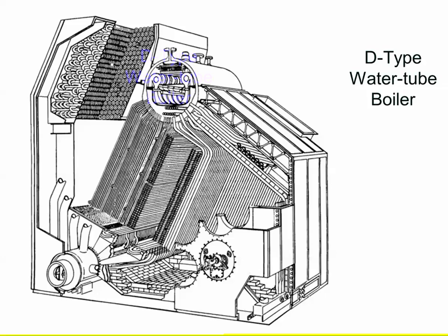There is nothing protecting the superheater tubes on light off except for the fact that you have a minimal fire, so the average combustion gases in the furnace are low. When you light the burner off in the simulator, you're going to light off at, say, like 15%, so I can have more assurance that it will light. But once it's lit, the answer to this is you drive the size of your flame down